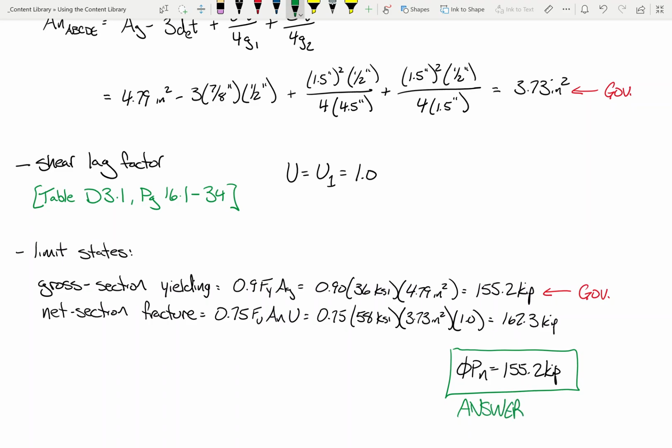That can happen. That's just the case. I have done bridge designs before where some of the math for flexural limit states is way more involved than this. And I have done problems where you go through all this math for lateral torsional buckling, and then you do a fatigue check and you find fatigue's what governs the design. That's happened. That's just the nature of the beast. That's just how it is. All right, anybody have any questions on this idea?